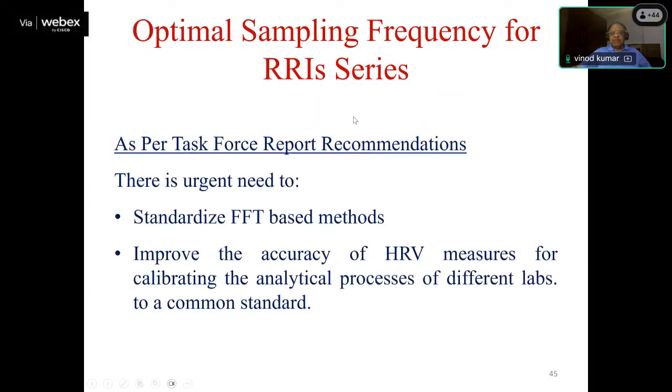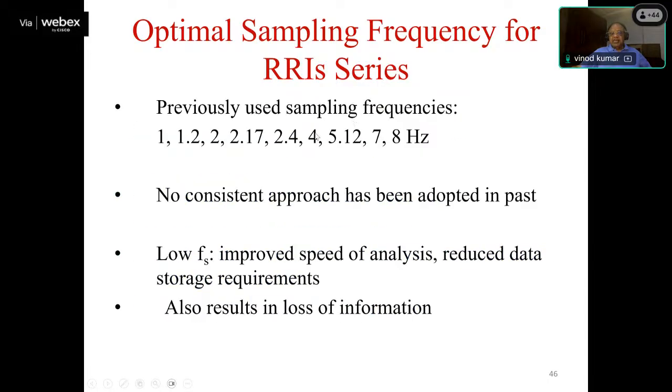What should be the sampling frequency? That is one thing. Second, what type of window function you have to use so that aliasing is not there. So we have used different window functions. Many people have done work in that area. They have used different window functions and different sampling frequencies, and the optimal sampling frequency and window function have been selected.